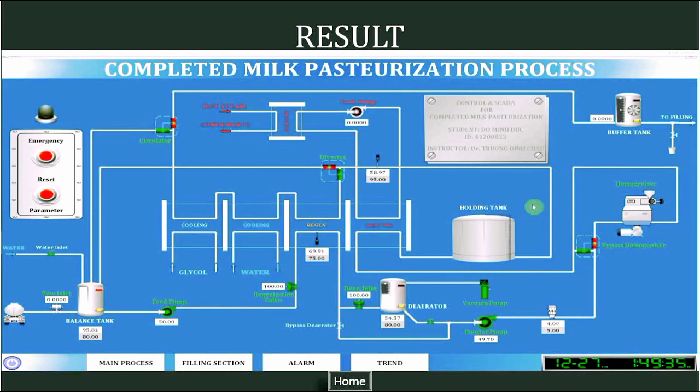And this is a high pressure homogenizer. There are many valves and pistons in this device which will press the product to homogenize the fat and the milk together, because there is always fat in the milk, and the fat may be curdled at the cooling section, and it will stick in the pipeline and raise the pressure and damage the process.